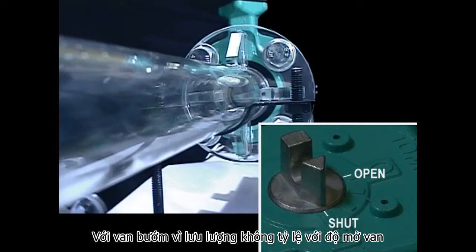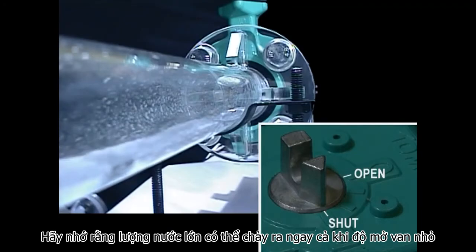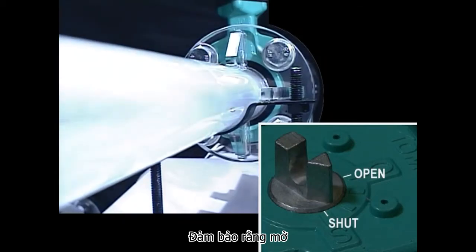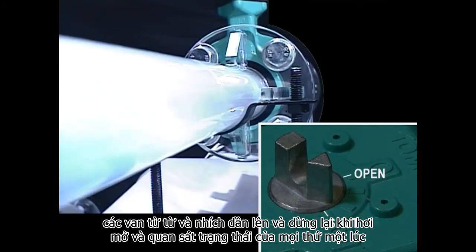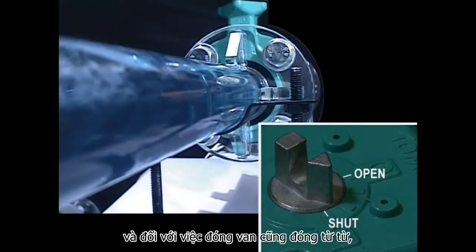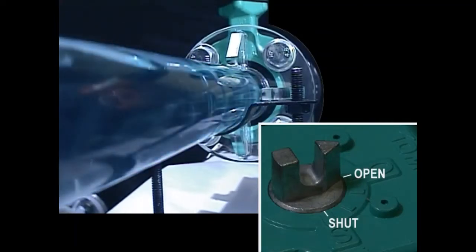With butterfly valves, since flow is not proportional to valve opening, remember that a large quantity of water may flow even if the valve opening is small. In short, open valves gradually by inching. Stop when slightly open and observe the state of things for a while. For valve closing, also do it gradually by inching. We can go so far as to say that most of the troubles associated with ballast operations can be avoided unless you open and close valves abruptly.